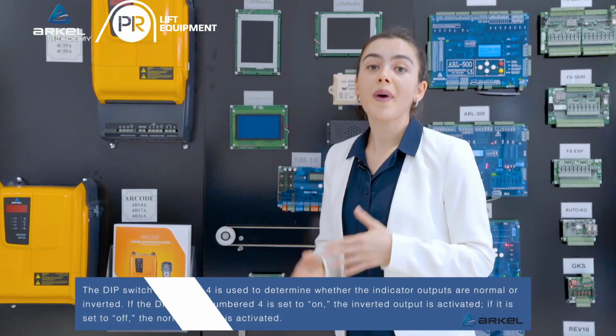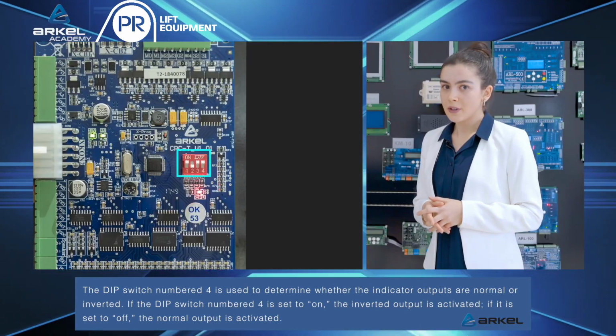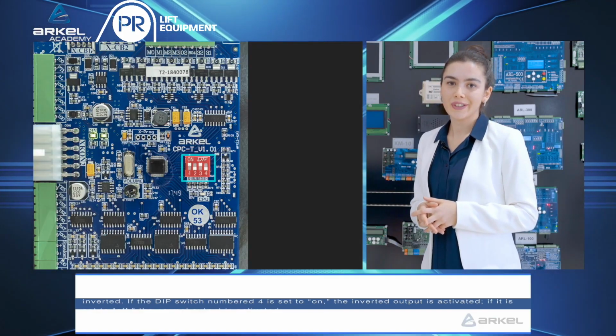The dip switch numbered 4 is used to determine whether the indicator outputs are normal or inverted. If the dip switch numbered 4 is set to on, the inverted output is activated. If it is set to off, the normal output is activated.